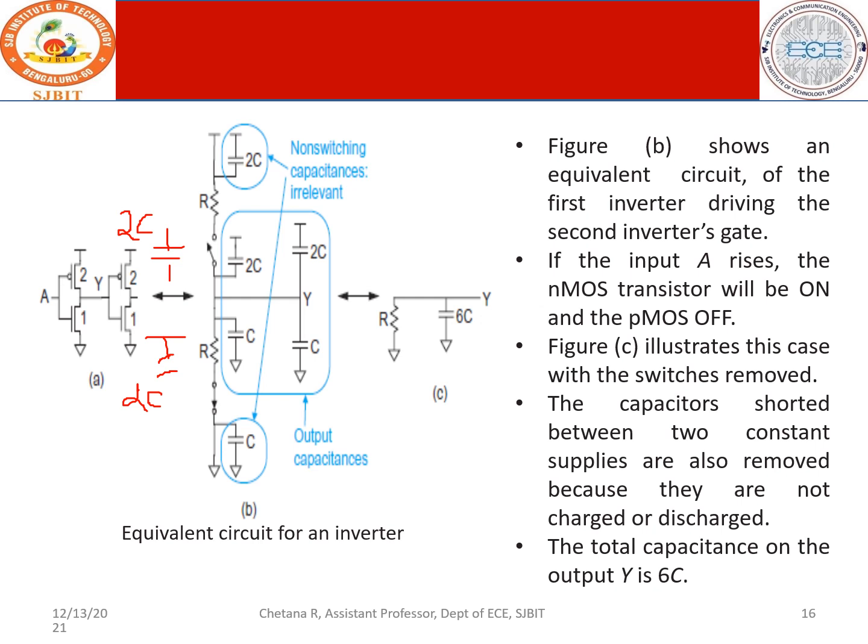Similarly, the ratio of NMOS is 1. Therefore, the width is 1. Here the resistance is 2R, so this in turn is nothing but 2R by 2.